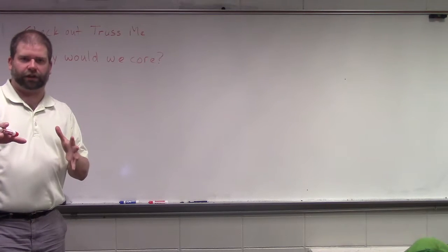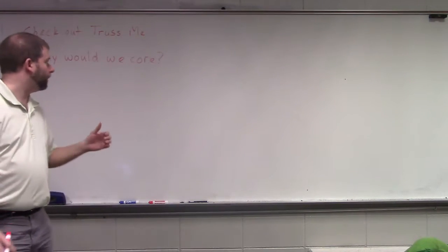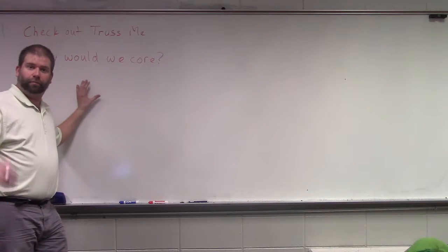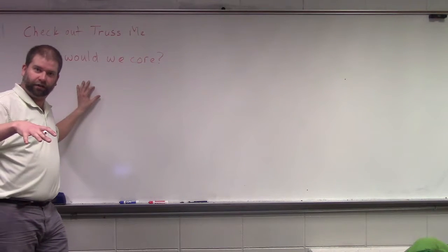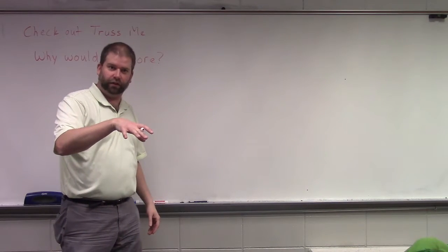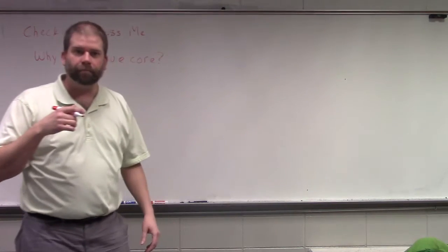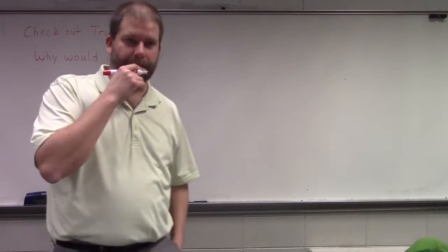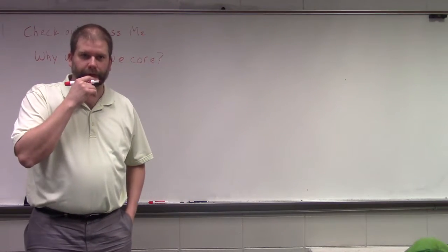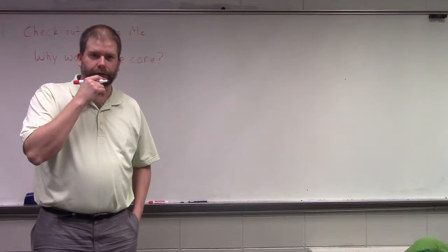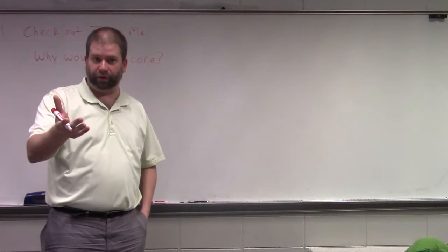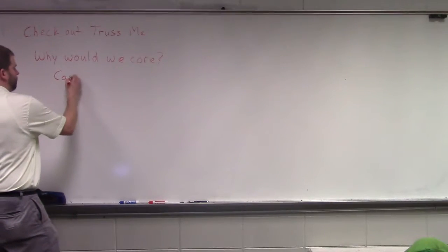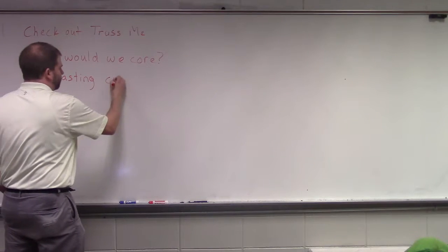So what I think you're trying to say, and I don't mean to be rude about it, is that you're using it to compare new concrete coming onto site against other concrete that's been placed? No, my thought was, if you have concrete coming into the site and you pour it, it cures, you can take a sample of that just to make sure you're meeting the project requirements. Yep, exactly. So the whole purpose of casting cylinders is quality control.